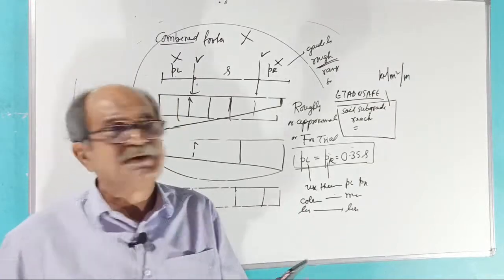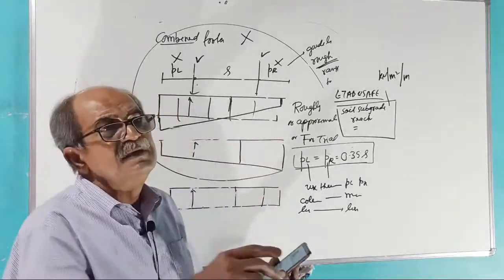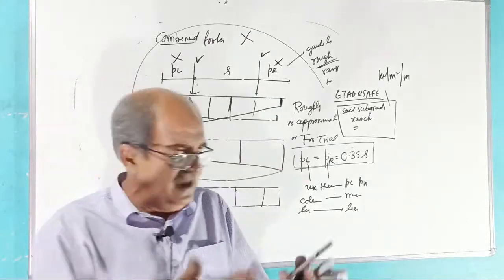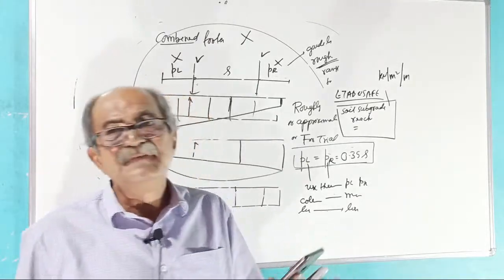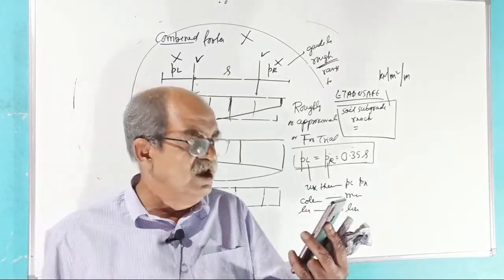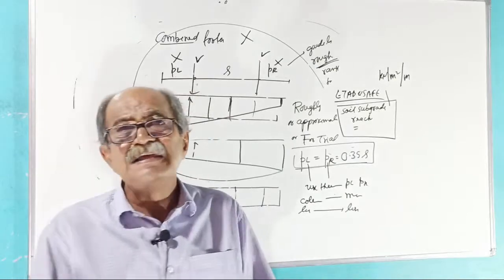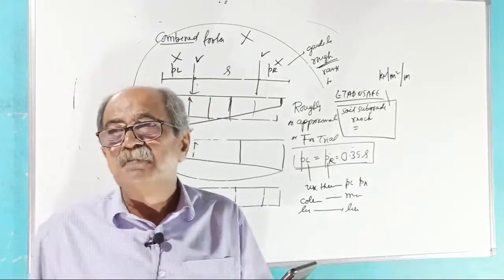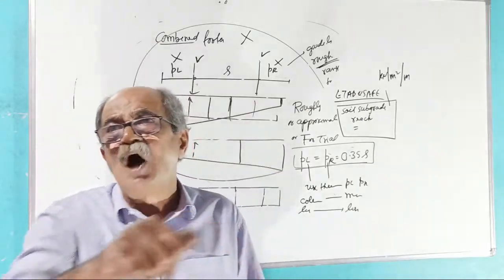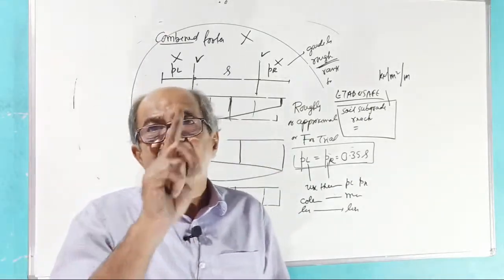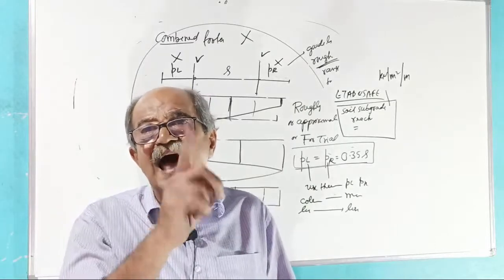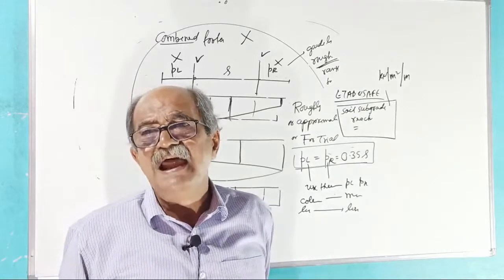No, don't give equal projection. If you give equal projection, CG will shift. If the load is more, give a little more projection. Tell me, what is the meaning of soil subgrade reaction? Tell frankly, are you knowing or not knowing? That value you have to give to the software. Then it will consider the settlement of soil, and it will give you exact pressure by finite element method.